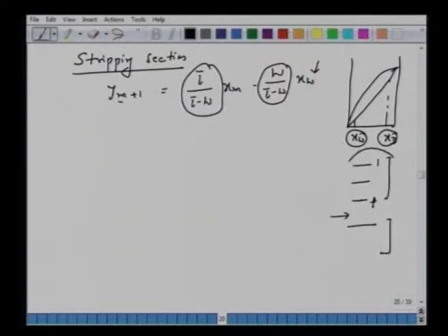One equation will hold good for all this, another equation will hold good for this. We can also write down one equation for this Q line. So that's the way you have to do it if you want to do it by programming. Here we are trying to write down this equation for every stage above the feed F and every stage below the feed F. So we have these general expressions.